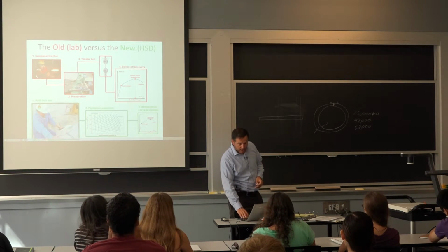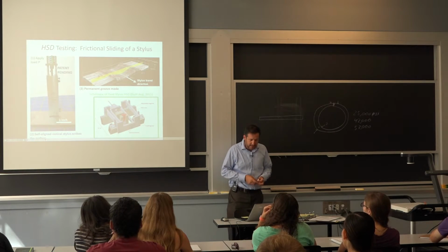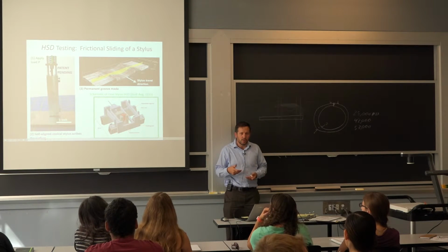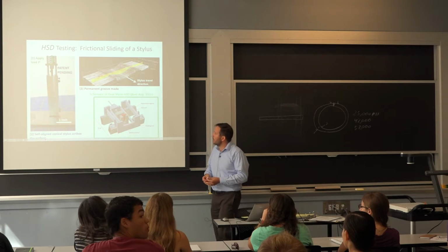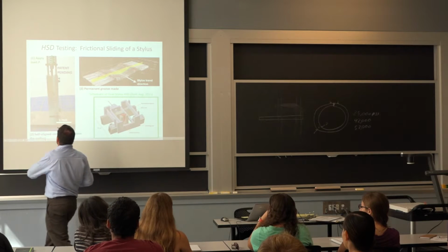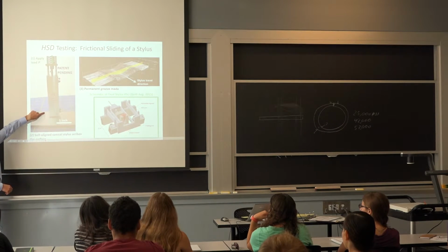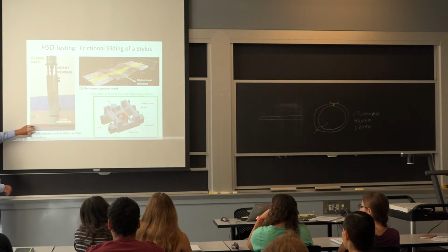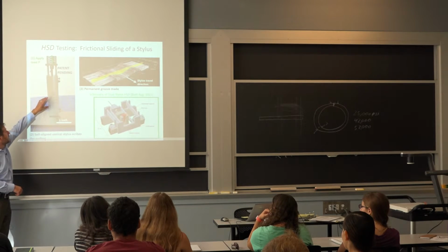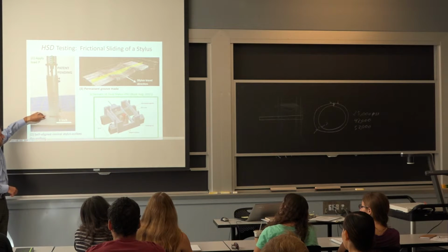Now, the way that it works is essentially by scribing the surface. So we have a stylus, it's a cone, and we apply a constant load. It creates a little groove indication like this. And what's very special about the technology is the core device is going to self-align with the surface.